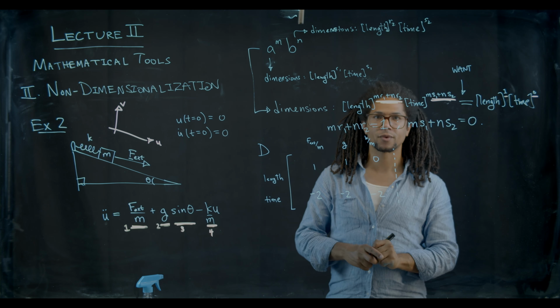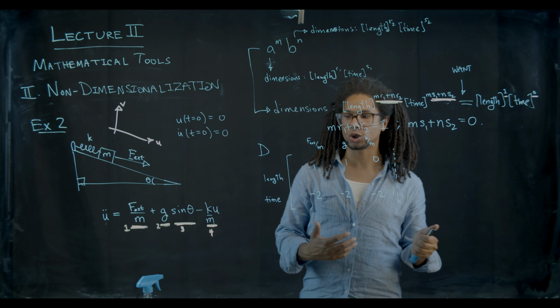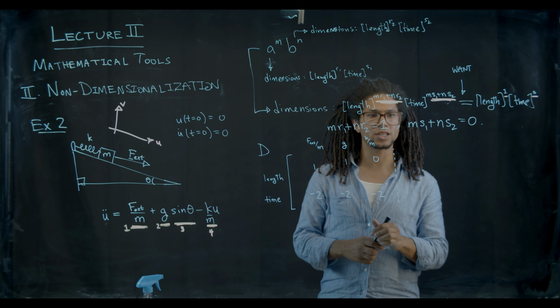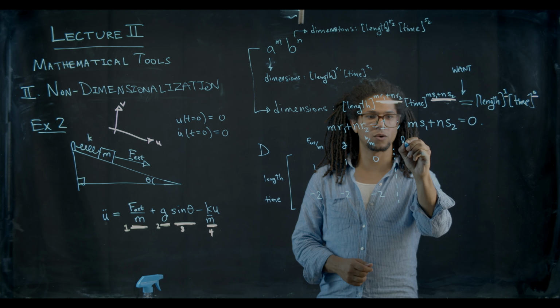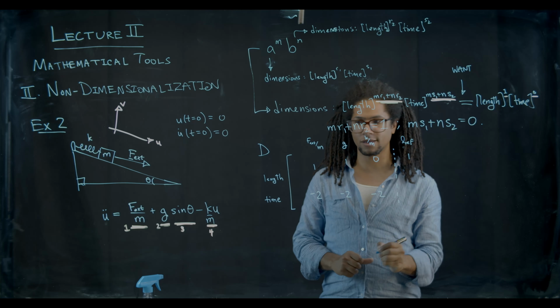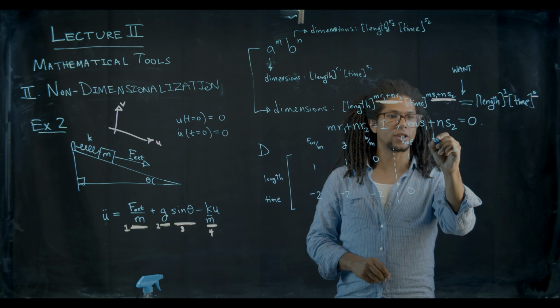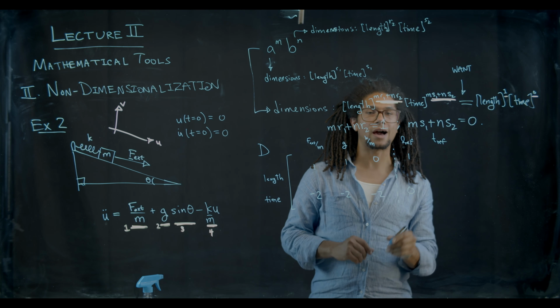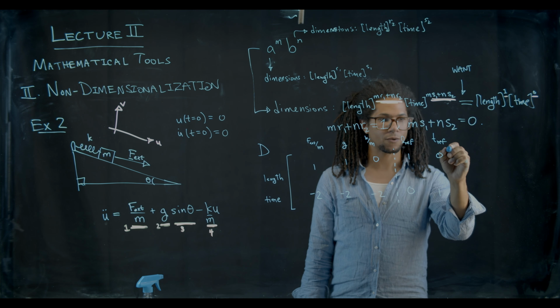The augmentation columns have the things that we want to solve for. So in this case, we would love to solve for the reference length, L ref, which has units of length and 0 units of time. And we'd also like to solve for T ref. We're totally allowed to do these at the same time. So this will be a 0 here and a 1 here.